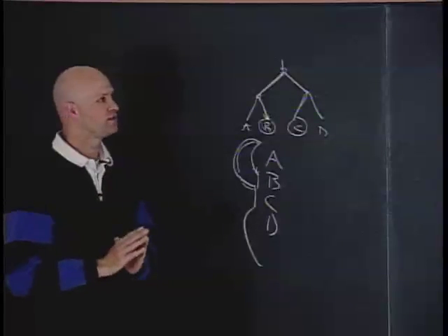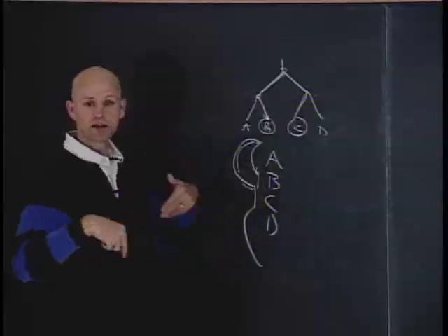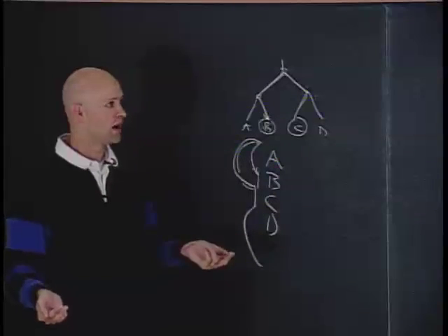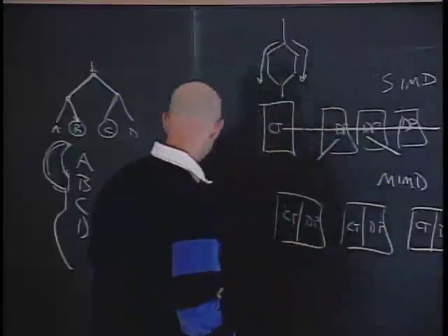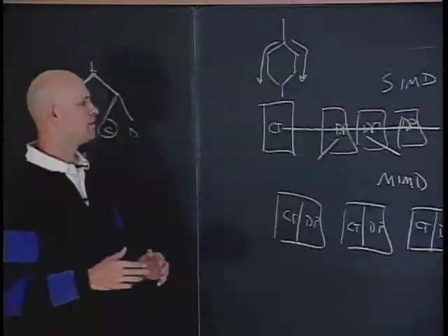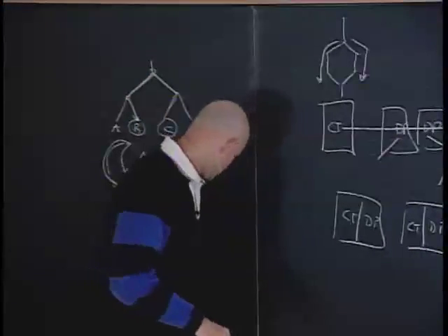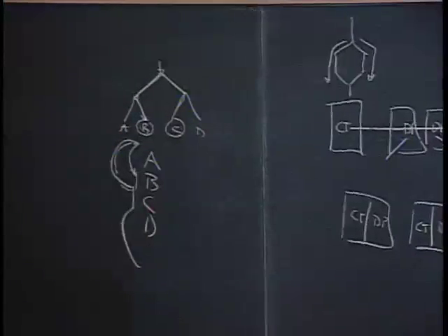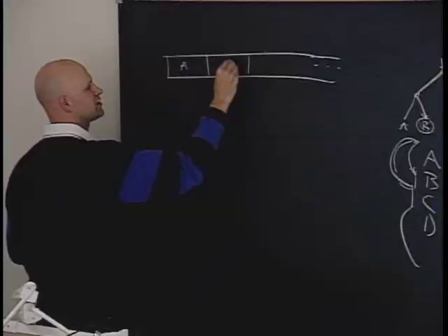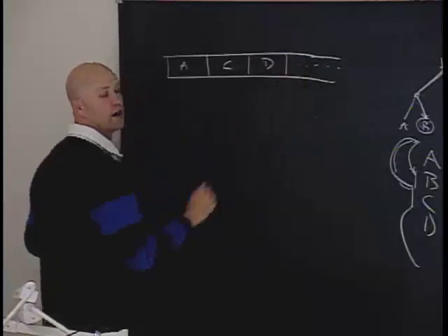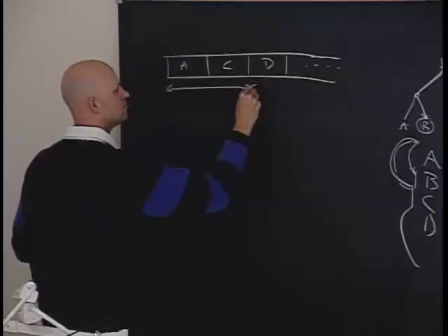Okay? I'll introduce one more piece of terminology, which is branch granularity. The question is, how many branches are running in lockstep at a time? How wide is this? You as the programmer would like that granularity to be as small as possible. Let's say you've got all these bits here, going off to infinity, and these guys want to run A, and these guys want to run C, and these guys want to run D, and so on. Let's say your branch granularity is this big.